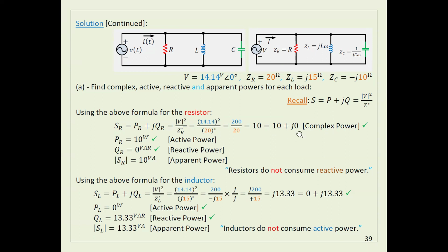And then, as you see here, I want to bring something to your attention, because some students made this mistake in test 3. Once we get a result in the complex domain, we transfer it to the time domain. But this is only for the voltage and the current. Some students did it for the impedance.